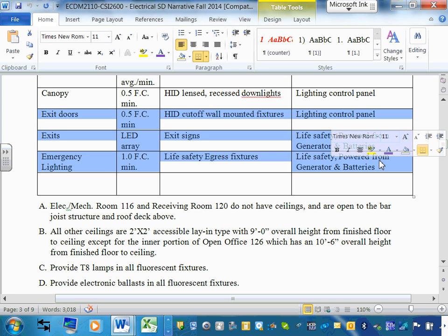What happens if I lose power? So we need to lay out an emergency. They call it bug eyes. You guys have seen the bug eyes. That's one type of them. Another type is a fixture like this with a battery inside it. So you lose the power here, there's a relay that switches to the battery, and the light instantly comes on. They have many of them. Of course, it costs money, but there are multiple alternatives of meeting the life safety egress light.